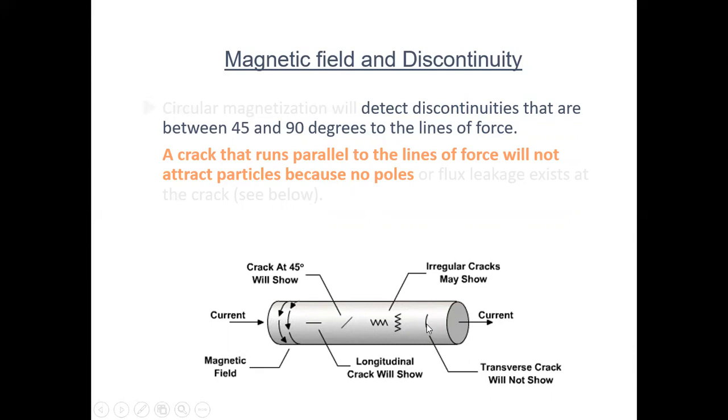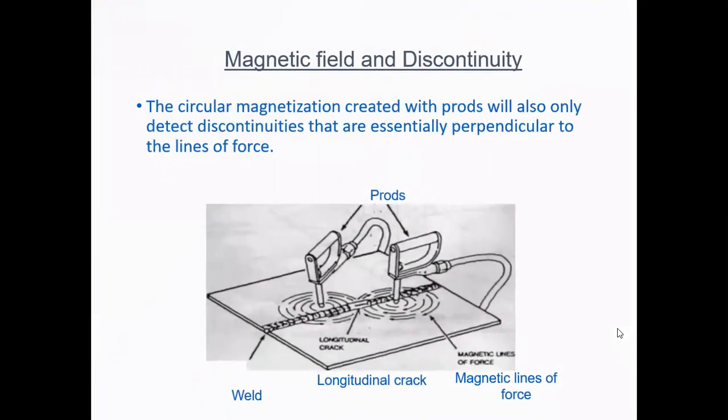So for this purpose we have to give a coil shot. In a coil shot the field will be longitudinal, and it moves like this. Now here it is making 90 degrees, so we can detect easily. So for one job, one shaft, we have to apply head shot and coil shot. Two shots are necessary. Then only we can detect all location-wise discontinuities.